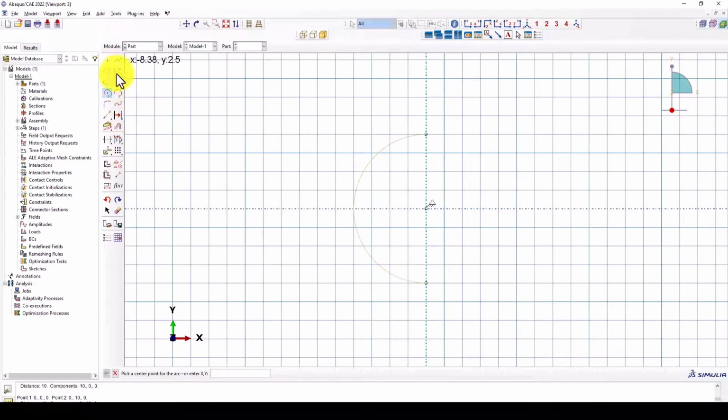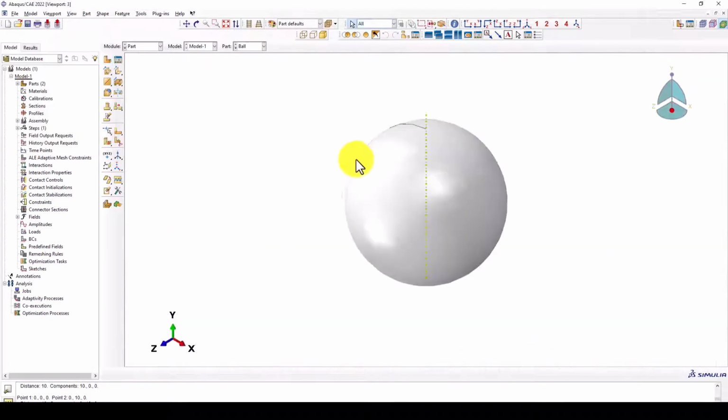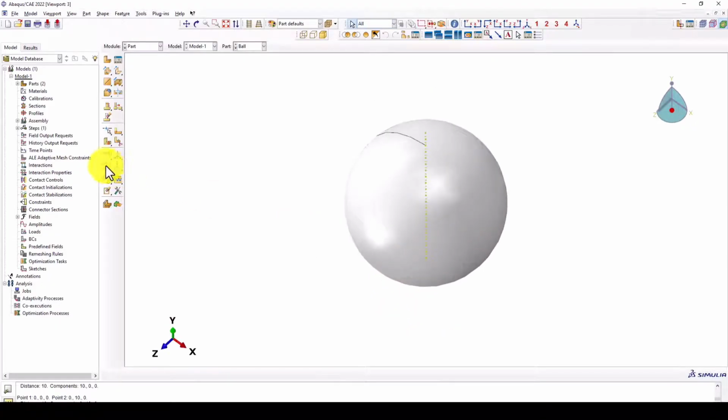Now let's compare low velocity and high velocity impact. In a low velocity impact, the structural response often has enough time to propagate through the structure during the impact event. We may see significant deformation, or we can say global deformation, bending, local indentation, contact pressure, and elastic or plastic deformation. High velocity impact is a different problem. It's an altogether different scenario.